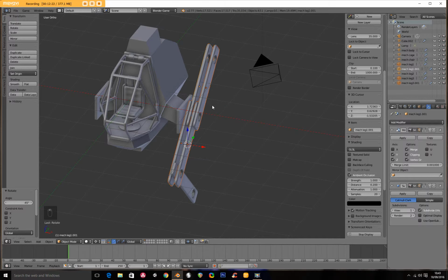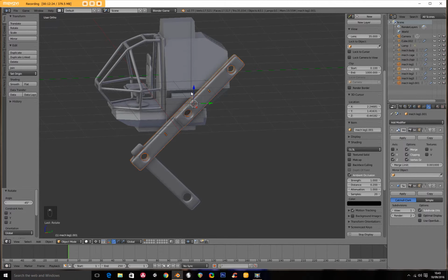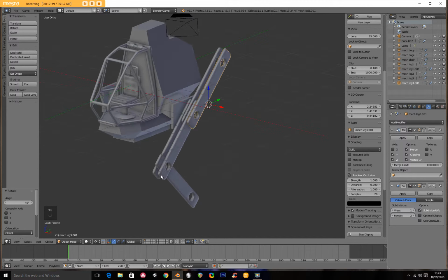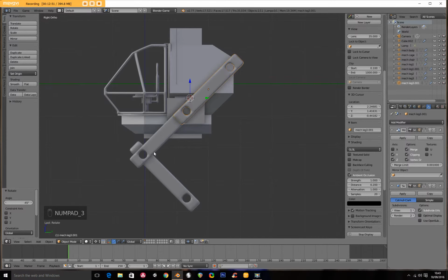So I want to hang weights off the top of this, so I just wanted to extend it first. There's other ways to do what I did there, but if I go G Y, it'll move on the y-axis, and G Y Y, it'll move on its own y-axis. So by pressing Y twice. So I could have done it that way as well. Probably would have been easier that way. Okay, so now we have something that's not miles away from what we wanted to make.